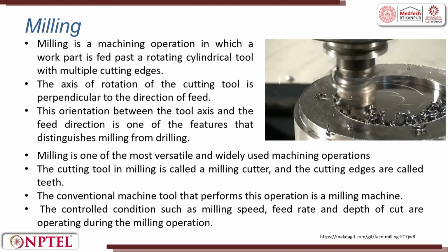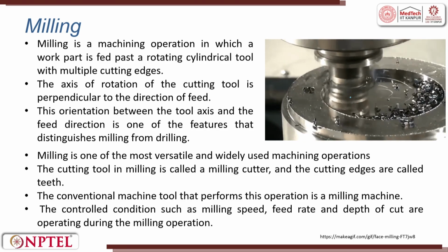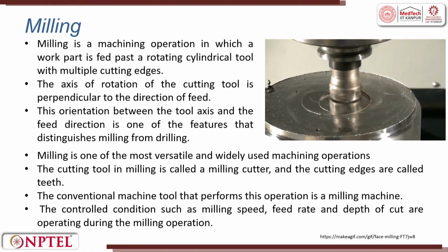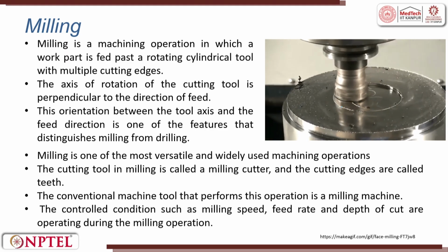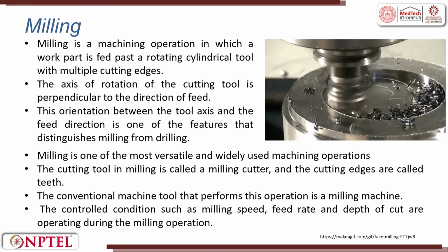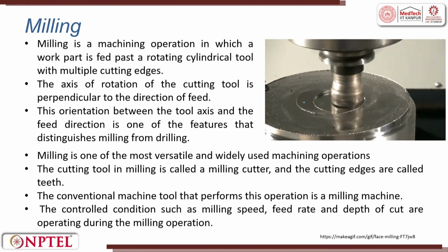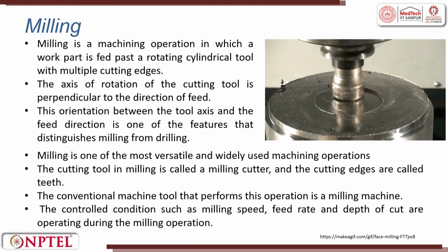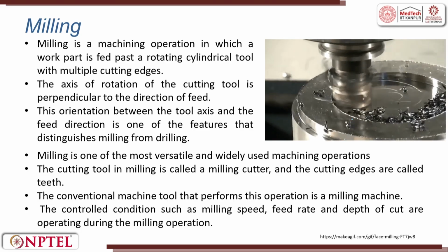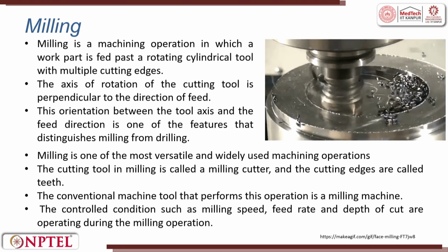Why is this phenomenon happening? Because the first cutter and the next cutter come in contact with the same place. So, you will have slightly longer, but smaller chips. And here it is also interesting to see the milling cutter face trying to machine and create a slot on the workpiece. And here it is trying to create a circular trajectory. It moves in a circular trajectory and you are able to get it.